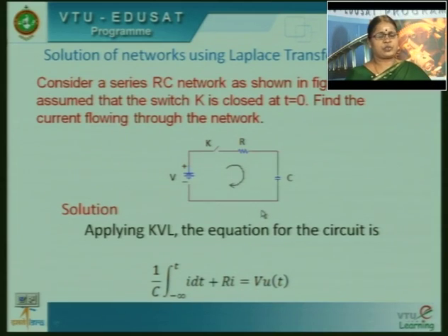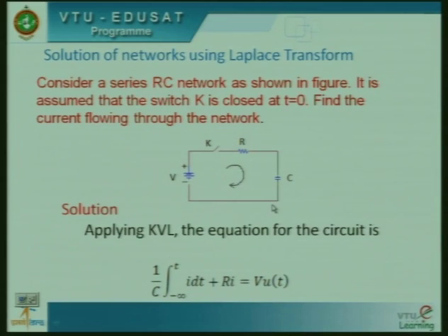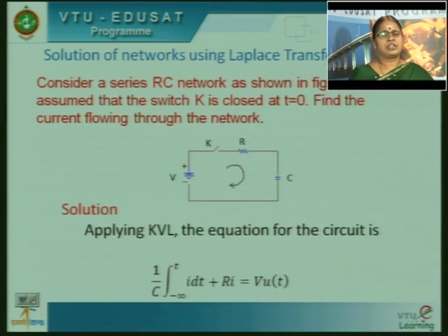Now, let us try to see how we solve the network equations using Laplace transform. To solve the network equations using Laplace transform, we follow certain steps. The first step is we describe the network with the help of differential equations. Once you know the differential equation, we can take Laplace transform of the differential equation. If you take Laplace transform of the differential equation, the resultant equation is an algebraic equation in frequency domain.